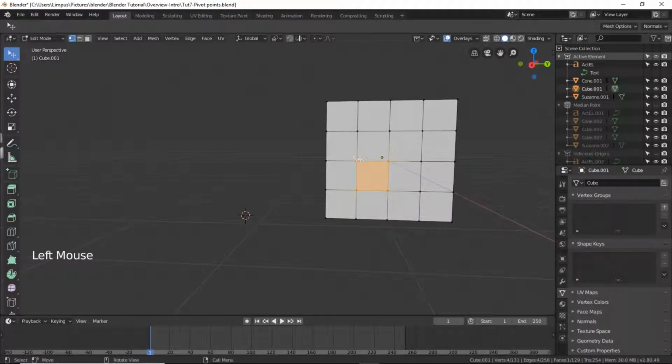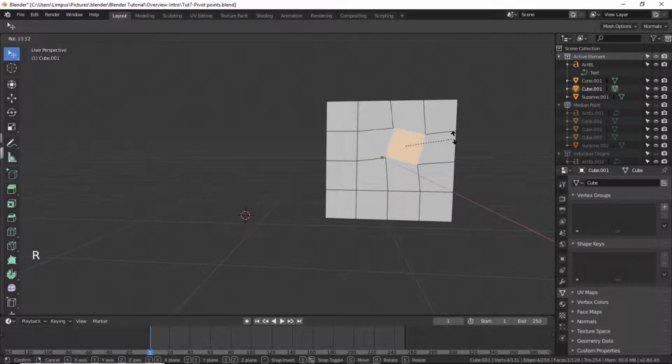When two vertices are selected, they form an edge. Four edges connected by vertices form a face. Using the active face as a pivot point in edit mode may seem complex, but all the possible transformations follow a few rules. The pivot point is always at the median of the active face. The transformation occurs by transformation of the vertices of the selected face.